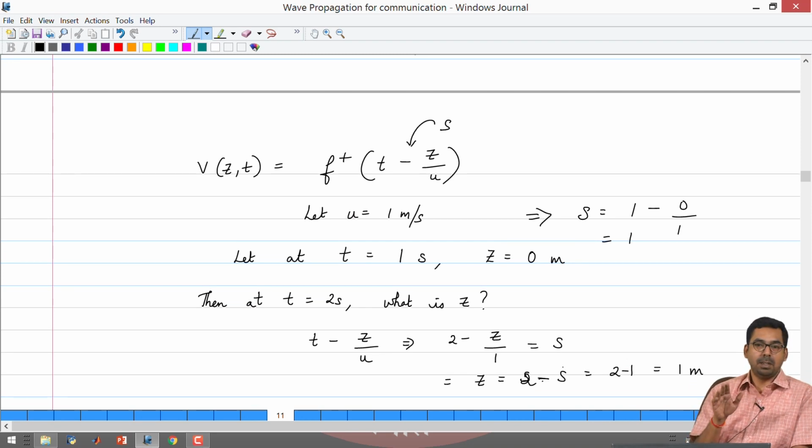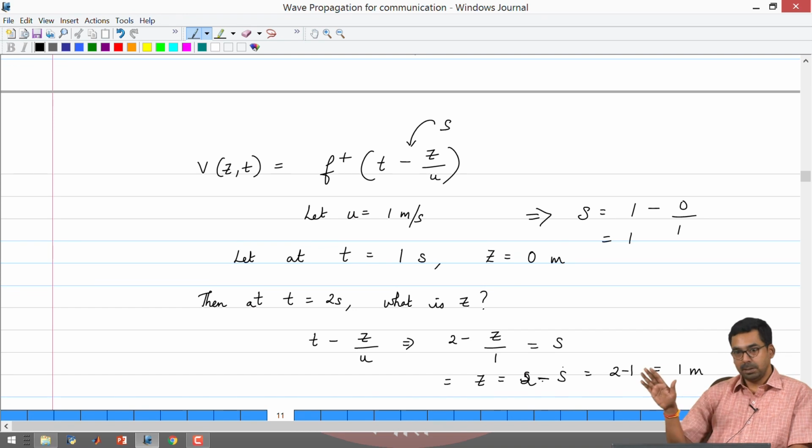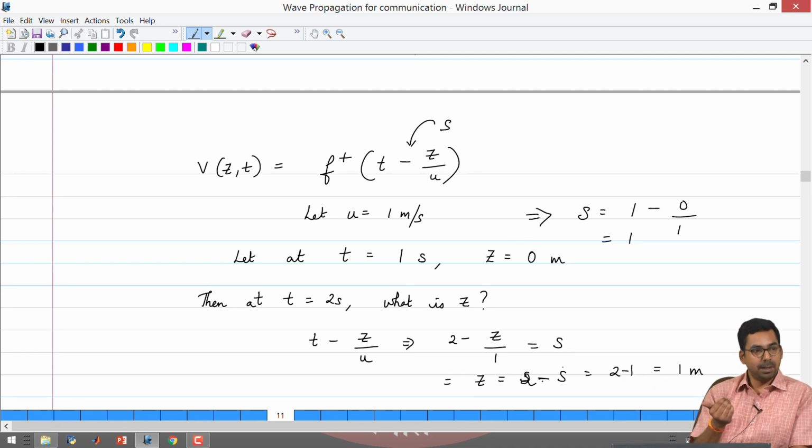We do not talk much about what happens when it is getting reflected back, but here it is very critical. So, this means that we have to design in such a way that the entire voltage which is traveling from source to sink actually has a possibility to get reflected back and then travel towards the source backwards, while the source is actually supplying some constant voltage.